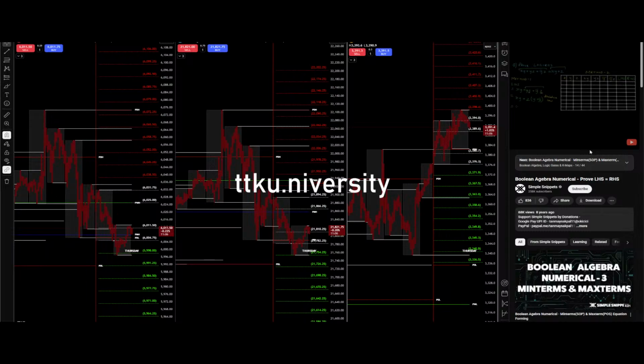Now the next step we get is X, Y or Z and 1. Now how did I get this 1? We know Y or Y complement is equal to 1. Now this is due to the complement law. So the next and the last step would be X, Y or Z, since anything and 1 is equal to that thing, and this is the identity law.